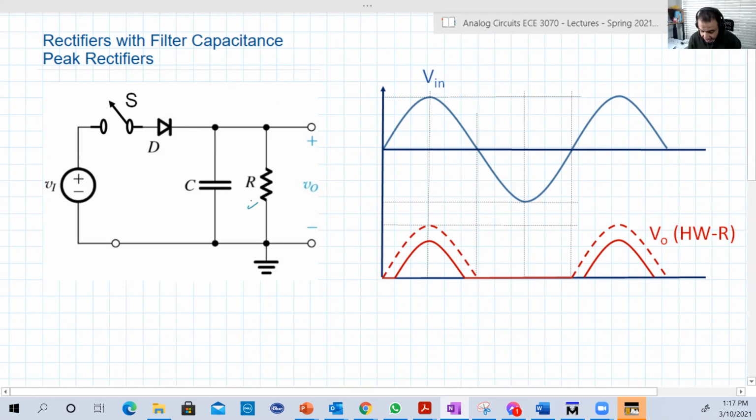The output of the previous circuit was just constant. Between 0 and that point, which we call T.7, at which the input reaches 0.7, the diode will be off, so the capacitor will not charge or discharge and will keep its voltage, which is 0. Initially VC is equal to 0.